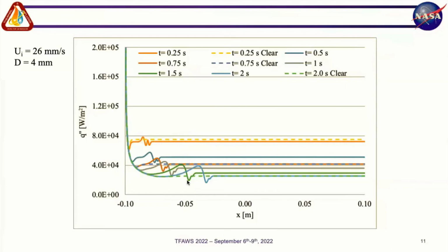And when you have the particle a little bit more downstream, you can see the location of the particle is here, and then a little bit downstream here, and so on, you have this large effect upstream of the particle. You have a very large enhancement of the heat transfer coefficient near where the particle is, mostly upstream, and then downstream you have a decrease in the heat flux that you would have without the particle. So here you have a conflicting contribution. It seems like the particle enhances the heat flux upstream, but is detrimental to the heat flux downstream.